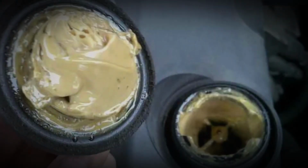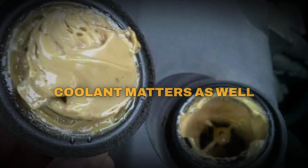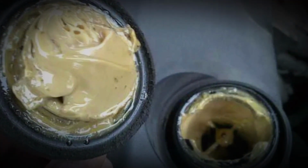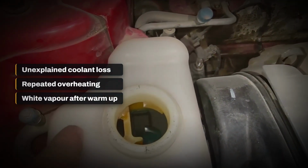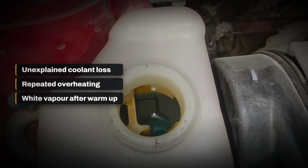Coolant consumption matters as well. A slow internal coolant leak may contaminate the converter even when there is no obvious puddle under the car. Watch for unexplained coolant loss, repeated overheating, white exhaust vapor that continues after the engine is fully warm, or other evidence that requires proper diagnosis.